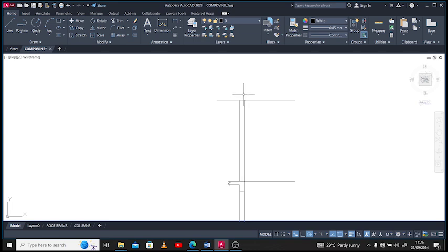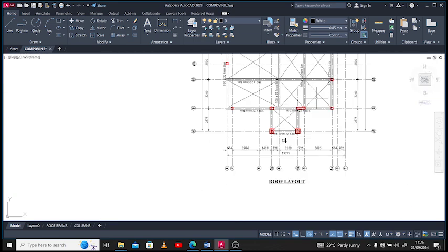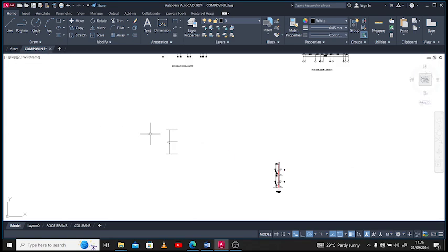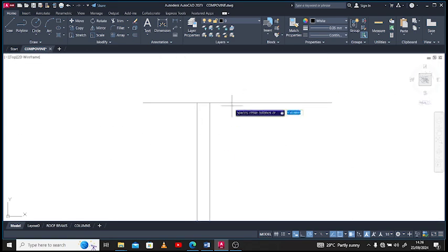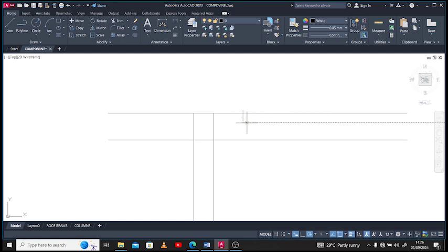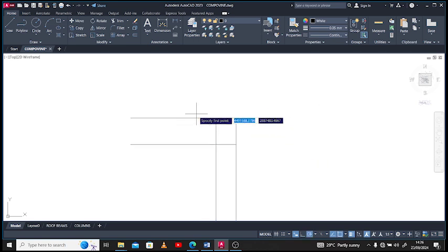Now the next thing we want to do is to get to the roof. What happens on the roof? We have the beam connected behind and then towards the left. Then you have to represent that in your drawing. That beam is a 300 by 250 beam, or a 450 beam. It could be 300 by 300 depending on the engineering judgment and your design considerations. We don't have continuity on this path, so we can just trim it off. We have continuity on this path, so you might just retain something around that path.